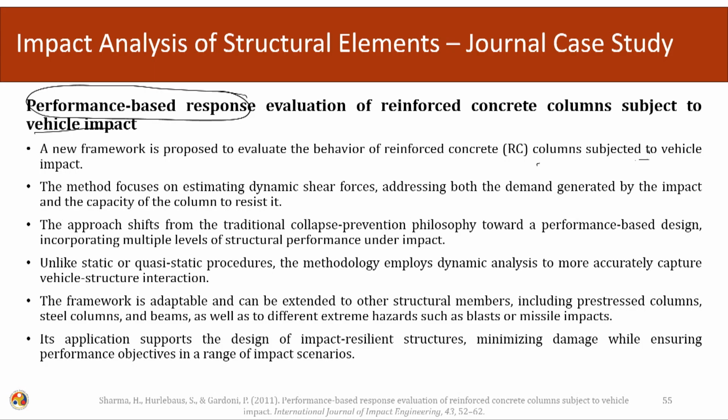Here a new framework is proposed to evaluate the behavior of reinforced concrete columns subjected to vehicle impact. This particular method focuses on estimating the dynamic shear forces, and it addresses both the demand generated by the impact and the capacity of the column to resist it. So, we are addressing both the demand and the capacity. Both these terms D and C will be required in order to formulate the limit state function. The quantity that is being used is the shear force, so the whole formulation is being done using the shear force.